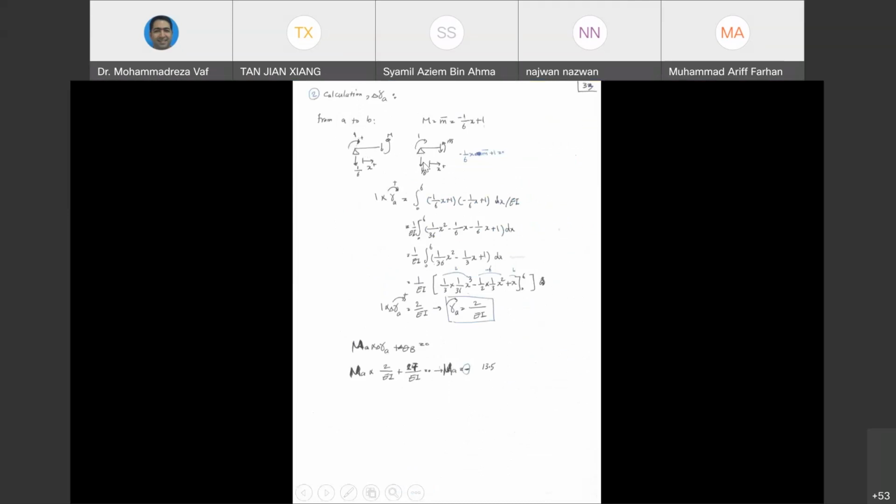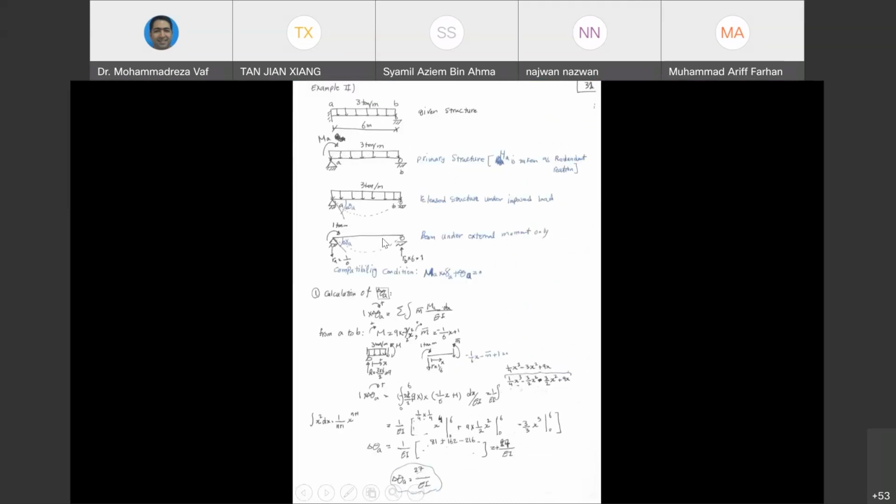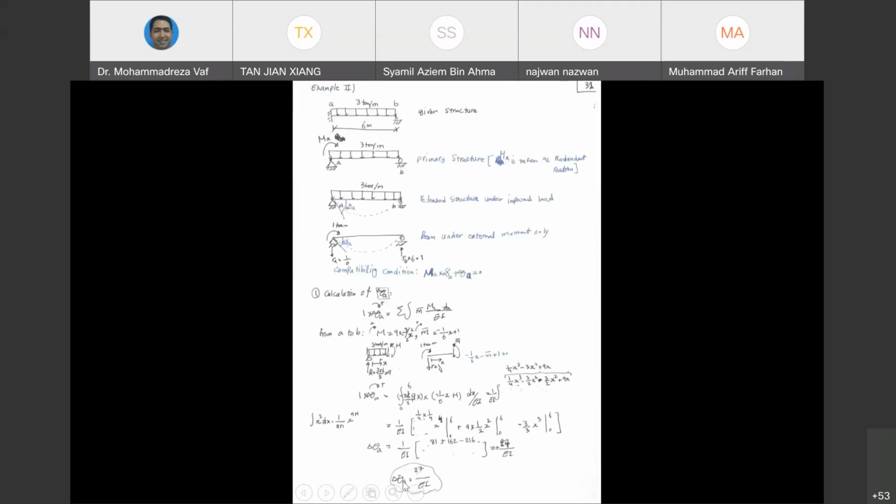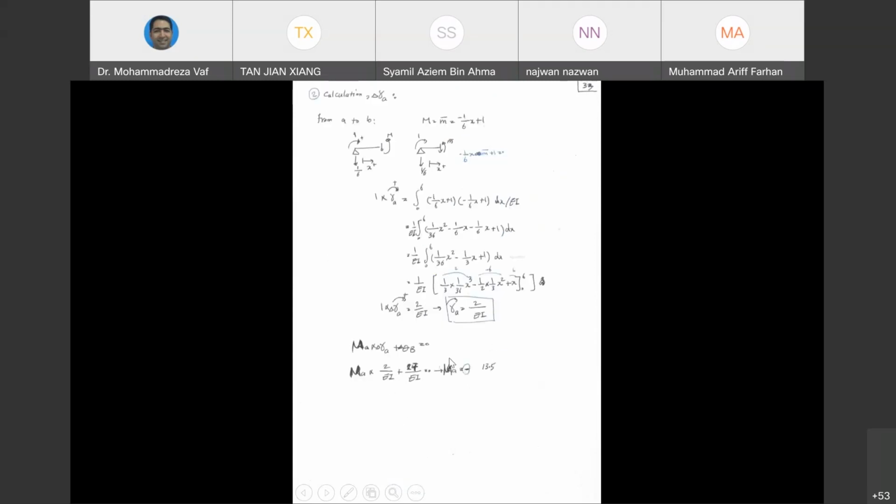You can see here again, the equation of M and M bar for the second structure will be the same. So right now we can say that M equals M bar, and the value can be easily calculated by writing down the equations of equilibrium. And finally, we get gamma A after you put all this calculation inside the integral. So you get gamma A, you get delta theta A, and you put them back inside the compatibility condition, and you get how much is MA.